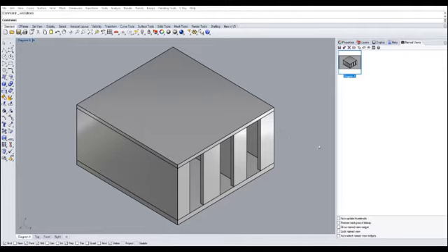So tune is a very special type of shader in V-Ray Rhino. It has a distinct outline to its material, whereas the regular white base generic material is just simply a solid geometry. So if we combine both, your render will not only have a solid part, it will also have an outline part, same way that we've been drawing all of our AutoCAD drawings.